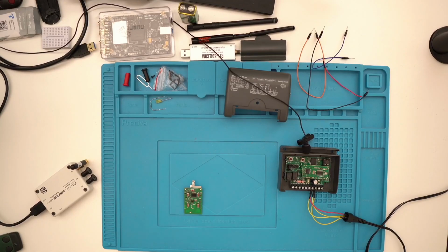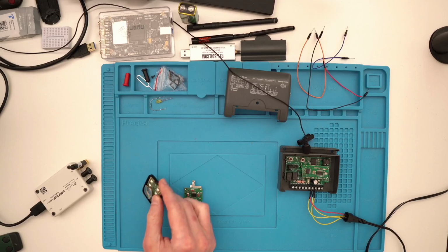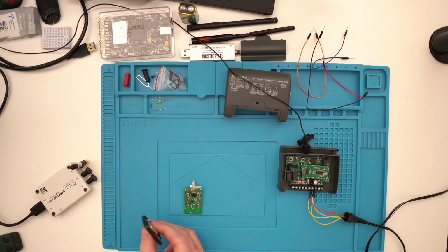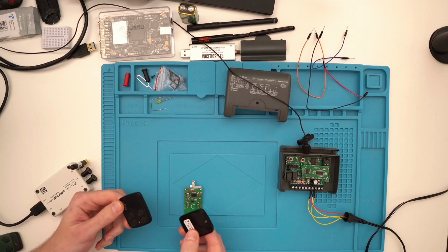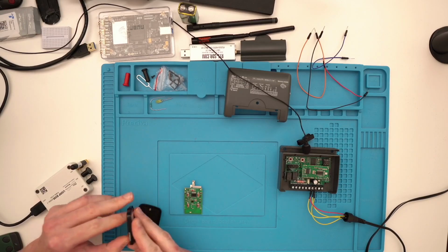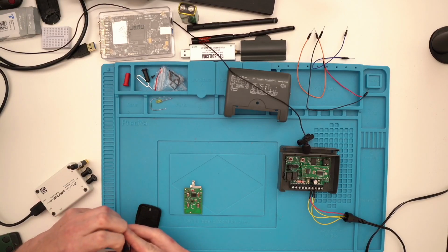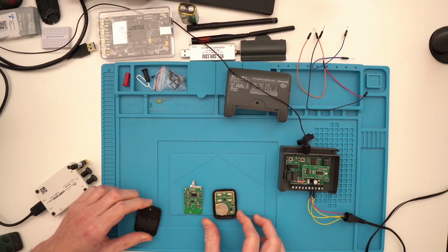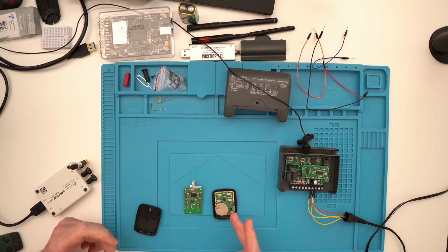And so what I did is order another remote that is a little bit simpler, the remote from Why-Ever, which actually implements the keys that are used by the remote. So as an alternative, you can use this chip that is recognized as a reference. And so you can use the datasheet properly and dump what is in the memory of the microcontroller, dump the key and replay that.